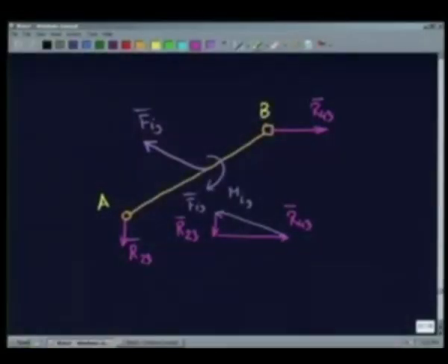So drawing the force diagram, which has three forces here, the triangle can be completed and the last unknown force on link 3 at the joint A can be found out by this. So therefore now the whole link is under static equilibrium due to the influence of the externally applied forces at the two joints and the inertia loading.